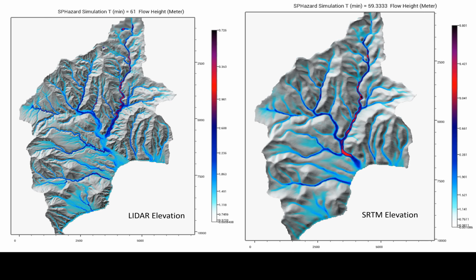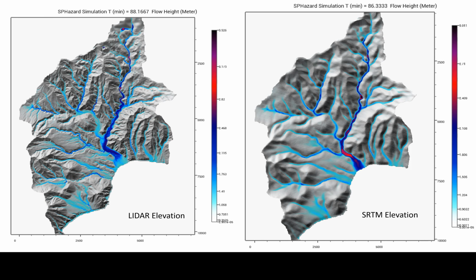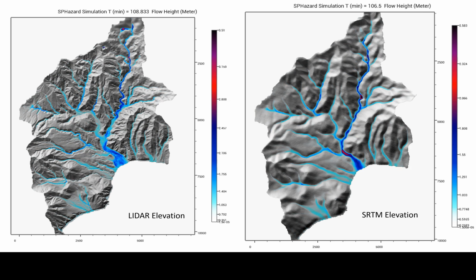But it's just that the general accuracy, the vertical reliability of the elevation data for LiDAR, for the laser scanning based elevation model, is so much better that it's world apart in terms of its flood impact prediction in this area. Right, so level of detail and resolution doesn't say everything. It's also, do you have the data to effectively use that and benefit from that level of detail? And their LiDAR laser scanning based elevation data sets can make a big difference.